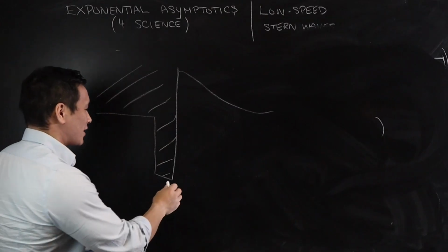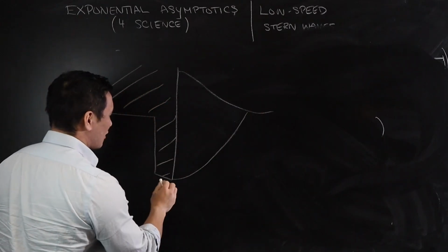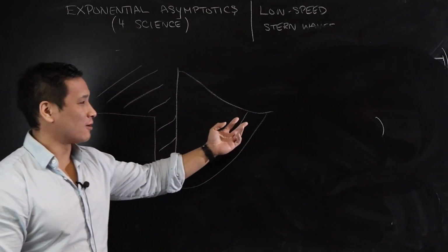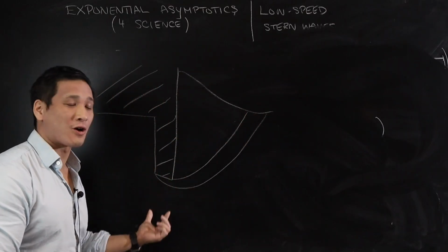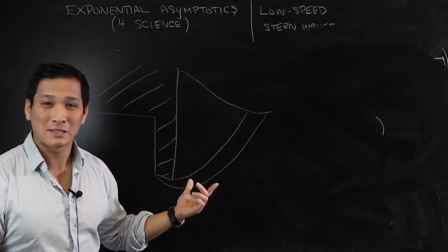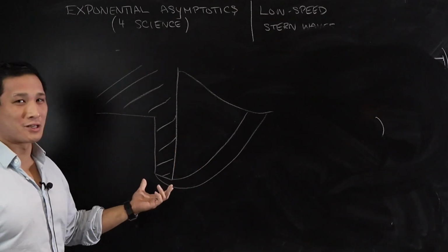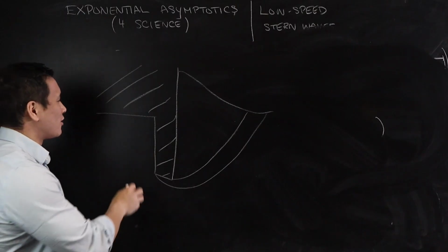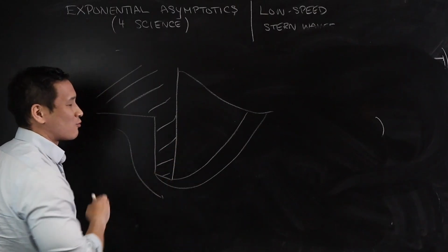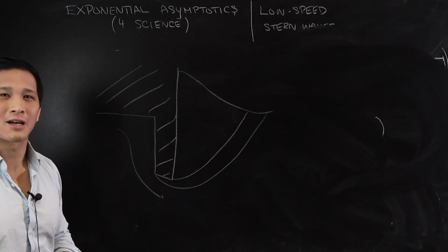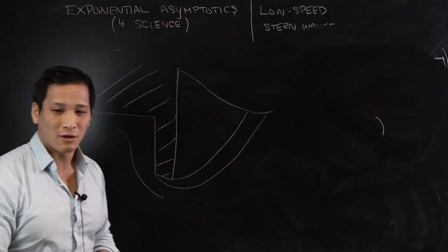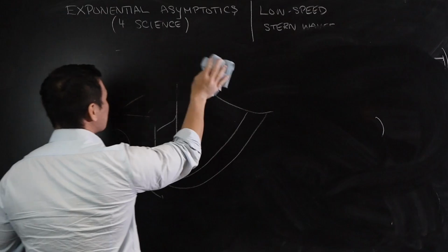because essentially there will be a Stokes line from this one, maybe a Stokes line from this one, but the magnitude of the wave that's switched on, because this is so far down from the free surface, might be smaller. Obviously, this is an unrealistic flow because in this kind of regime, you shouldn't really be doing potential theory because you'll have all sorts of wave separation and flow separation. But the theory will still give you, nevertheless, the magnitude of those waves which are switched on.